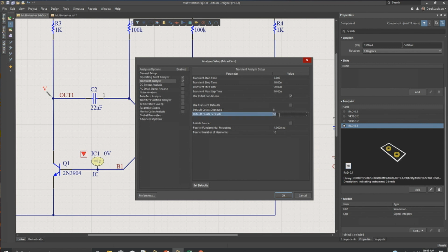And then you can specify the number of points per cycle. So you still have to do a little math. If you have a really fast source, you want to get more points in there. I was experimenting with at least half of the waveform, but usually, if you have a 1K, put at least a quarter of the waveform as the number of points. So 1 over the waveform frequency times at least a quarter of that number.